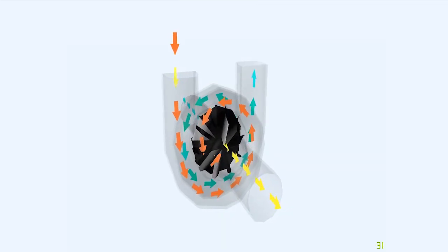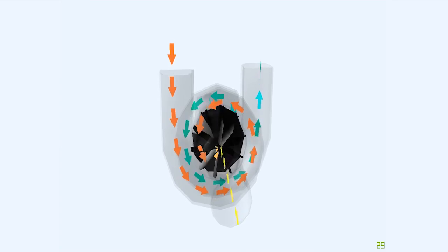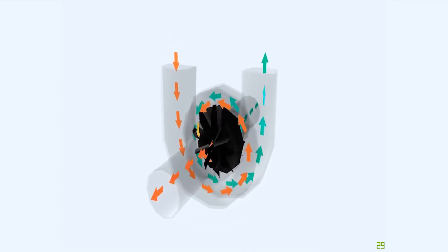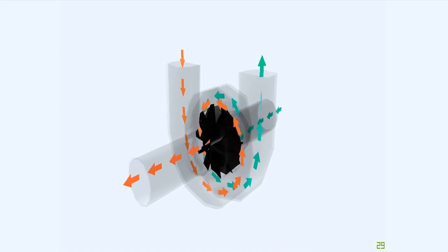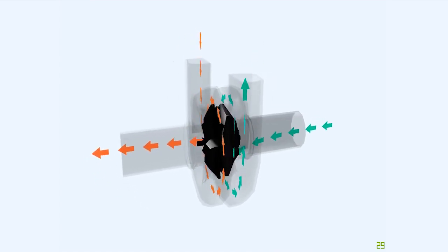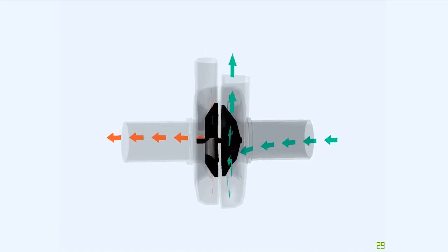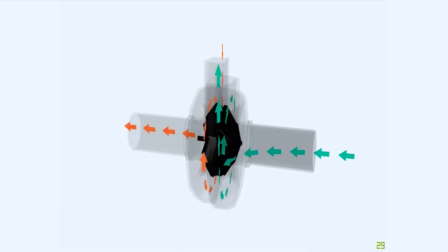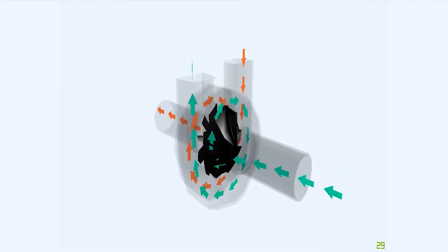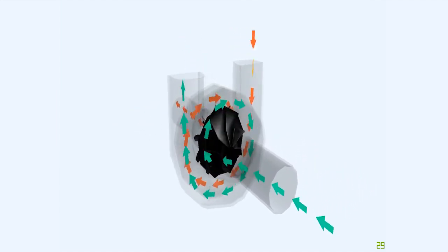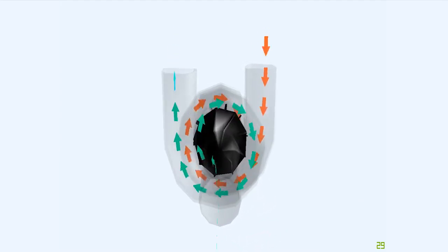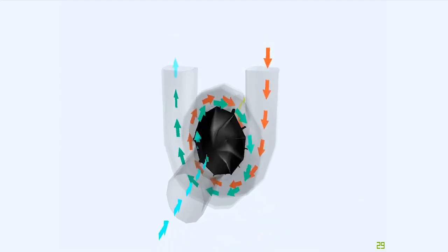With a fixed orifice system, it must be borne in mind that as the throttle is opened to gain more manifold pressure, the increased exhaust gases which are produced as a result will cause the turbine speed to increase in response. This will trigger a further increase in charge weight, which will generate a further increase of exhaust system pressure. With this type of simple system, this chain reaction, which can be brought about by rapid movement of the throttle, may induce the occurrence of overboosting.